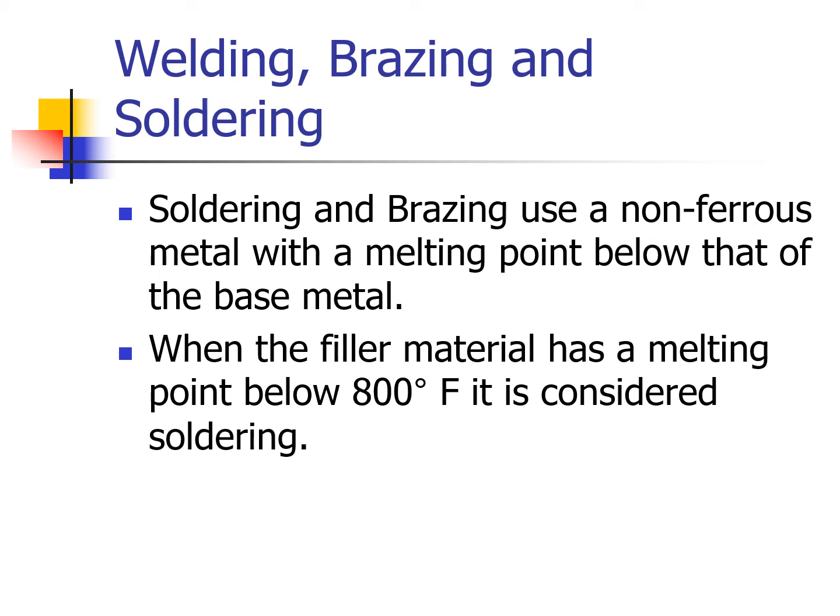You put the wire in on each side, and then you just squeeze it with a crimping tool, which is sort of a pliers, but shaped to grab it and hold it down. Again, being old school, I actually soldered every connection. The soldering is more time consuming, but I'm familiar with doing it, and I've been doing it for many, many years. So that's what I did. I ended up soldering stuff.